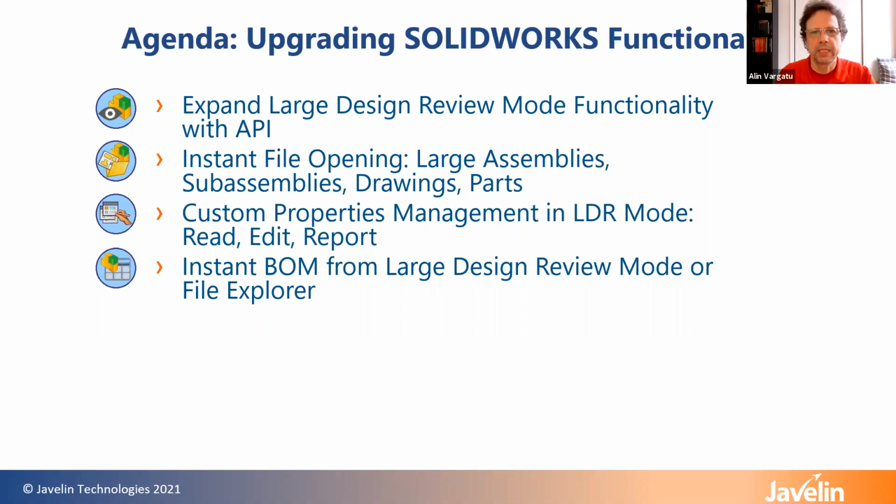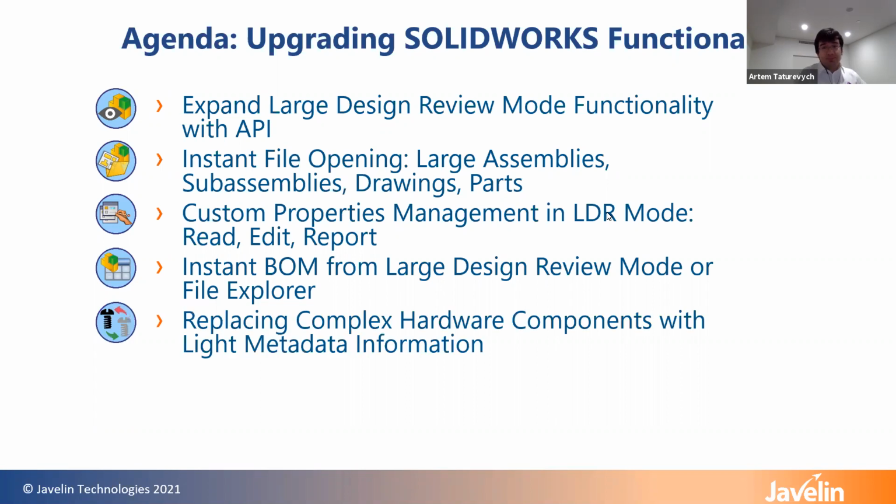It's pretty crazy. Yeah, we're all similar to properties. We're also going to show you how you can instantly access bill of materials from your assembly opened in large design review mode, or even directly from Windows File Explorer without the need to actually have SOLIDWORKS installed. And you can export that data to different formats.